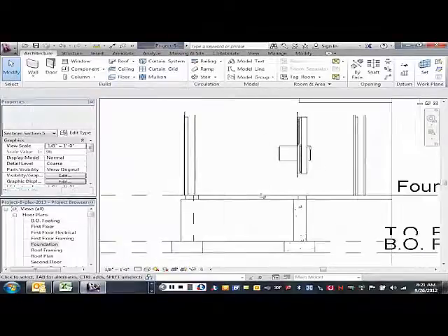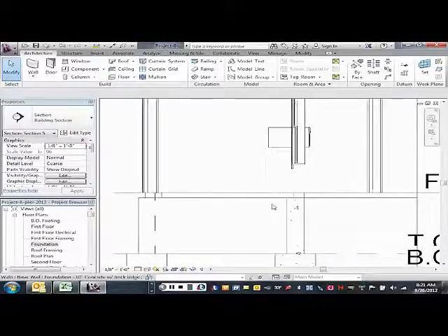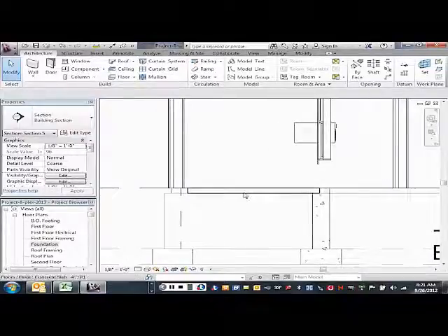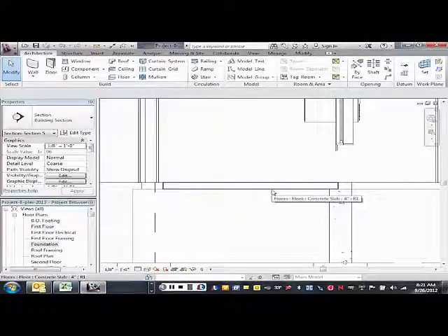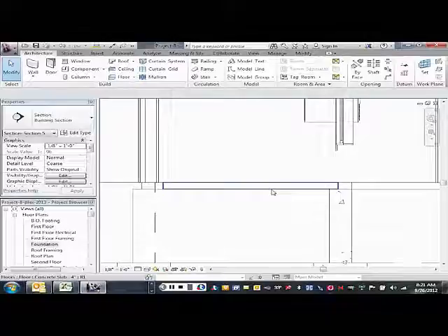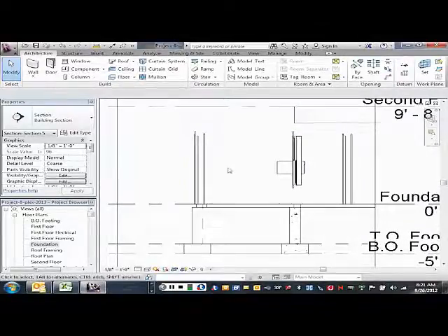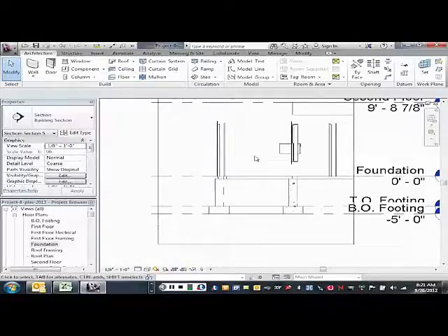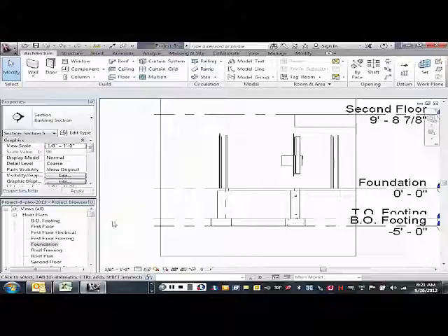here. We'll talk about this issue that walls aren't showing up here in a minute. But here is that patio slab right there. And you can see it sits in on my brick ledge. So when I highlight that blue line, it's sitting right in on my brick ledge, and it goes out. Okay? So the question about things not showing up on this view has to do with the fact that it's a structural plan, the foundation plan is.